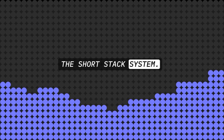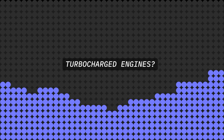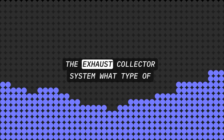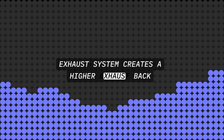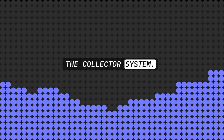What type of exhaust system is generally used on low-powered, non-supercharged engines? The short stack system. What type of exhaust system is used on turbocharged engines? The exhaust collector system. What type of exhaust system creates a higher exhaust back pressure? The collector system.